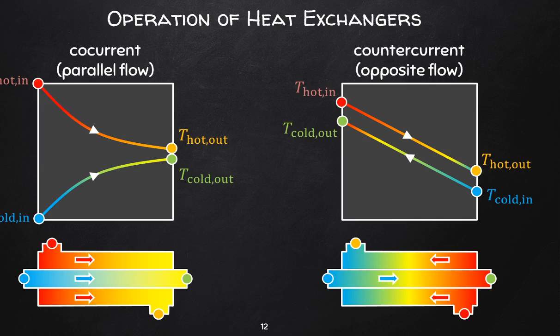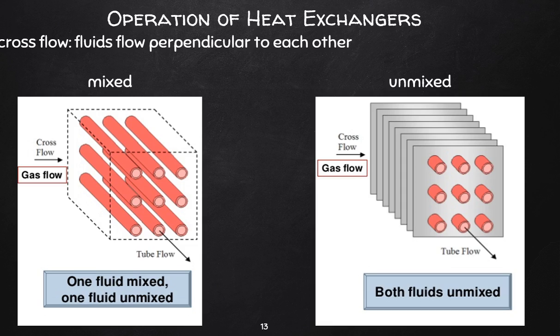And then when the fluids start coming out, you can control boiling much more easily using the co-current option. This is used in industry a lot of the time. So co-current has its uses, so don't rule it out completely, but counter-current is by far the most useful for us in most applications.